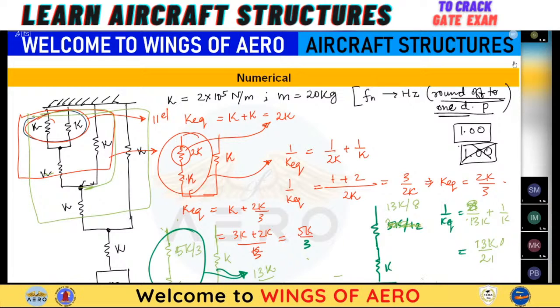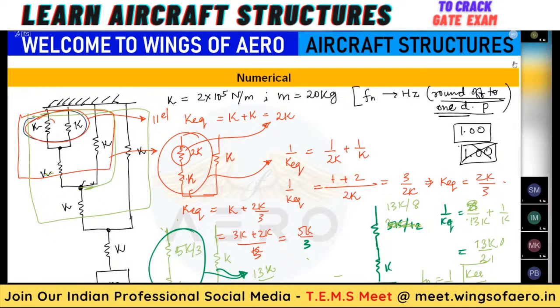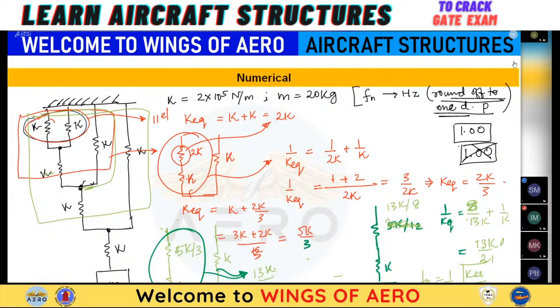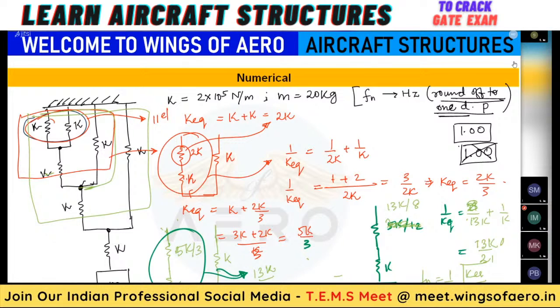So substitute the value: f_n equals 1 by 2 pi times square root of K equivalent by mass. And here again they have given us the answer rounded off to 1 decimal place. 12.5 hertz. Yes, which is within the acceptable limit.